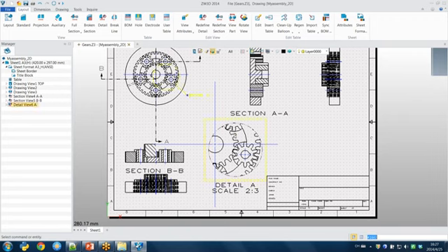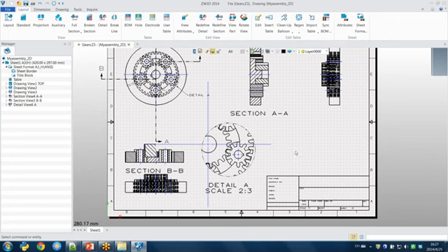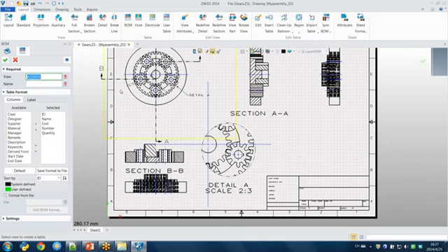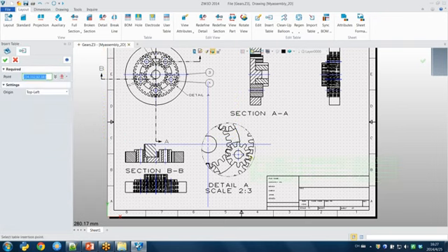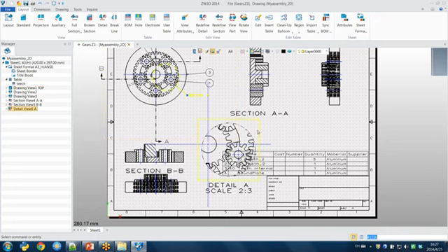And then after I finish the view design, I would like to create the BOM. So I can insert the BOM, select the view, and give a name. So you can find they have some variables to choose. For example, if I want to choose the material and the supplier, press OK. So I can insert the BOM table here. Okay, I change the position of the detail view. Just drag.